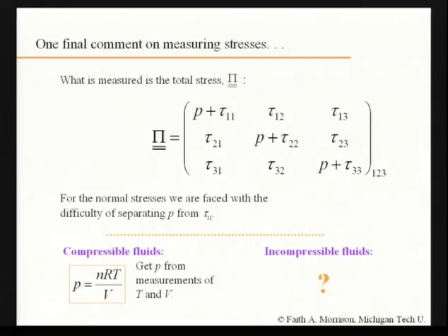Because, in fact, this is not a stress that shows up in the shear flow of ideal gases. If we did a normal stress measurement on a complex fluid, even then it wouldn't come, actually, because of the constitutive equation. It's not a problem for ideal gases because, actually, these stresses are 0 for ideal gases as well, which I can talk about later when we talk about the Newtonian constitutive equation for ideal gases. But for polymers, unfortunately, this pressure is very difficult to measure.